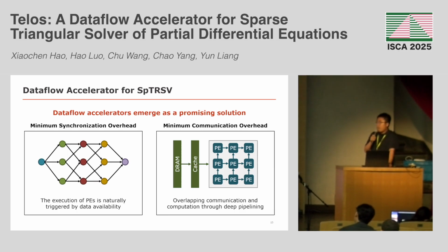Second, Dataflow accelerators are typically organized in a spatial structure, where PEs directly communicate with their neighbors. This results in a fixed and minimized latency for resolving dependencies, allowing communication and computation to be effectively overlapped. Consequently, utilization improves as PEs keep busy with eligible computations, avoiding stalls commonly observed in GPUs.